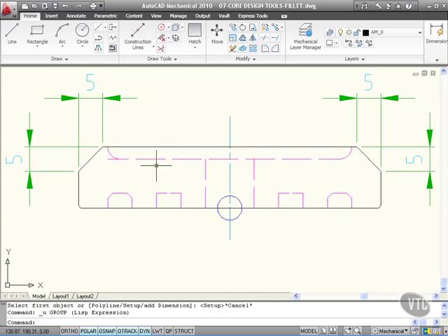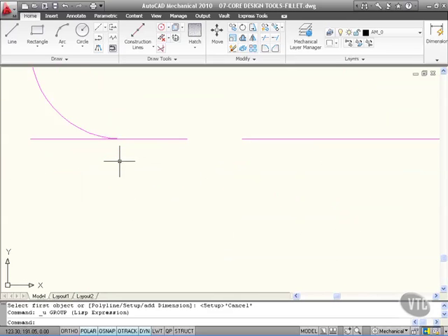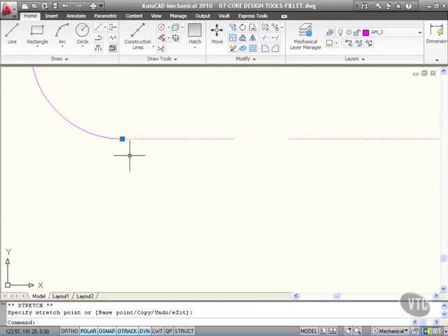So all I need to do this time is just click on that line there and take it to the end of that arc there. It's easy, but zoom in so you're nice and tight. Roll up on the wheel there on the mouse, select your line here and click on your grip and just bring it all the way along until you get the end point snap there on the arc. Click there like so, and it brings that line in.